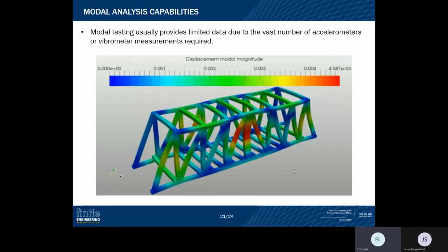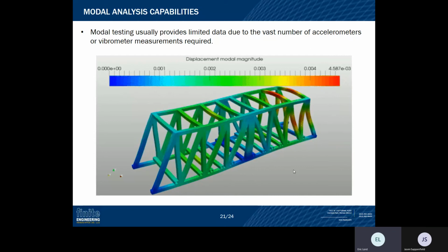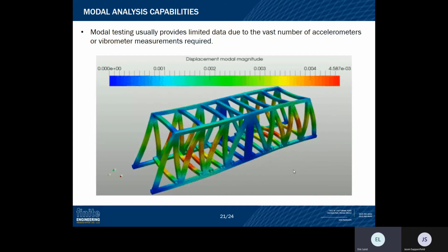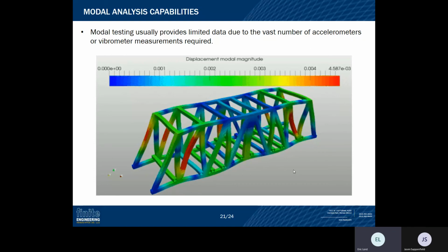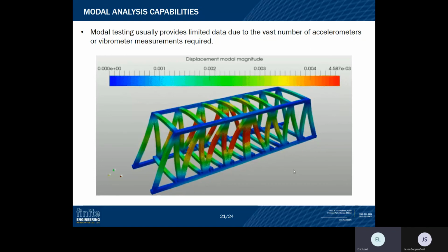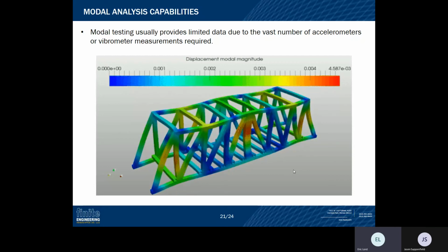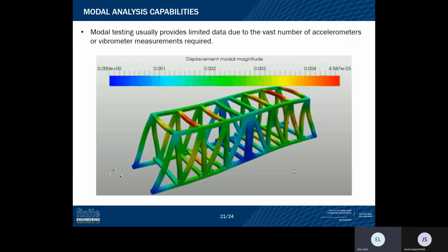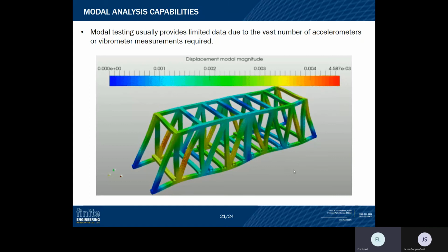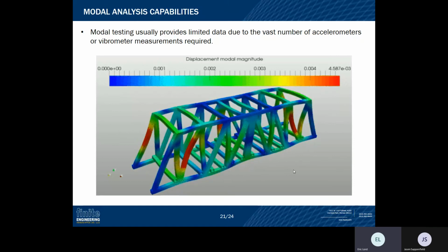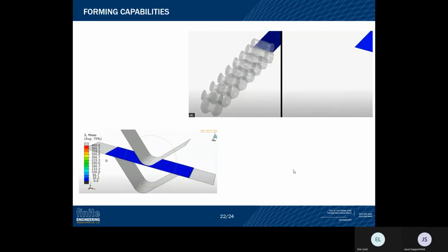We know how much loading, essentially, it's shifting around in terms of mass. The other thing that we know from our mode shape is that in one axis we might need to change something, whereas in the other axes we might not need to. So it provides a lot of insight that we wouldn't get from testing, in this type of analysis versus testing method.